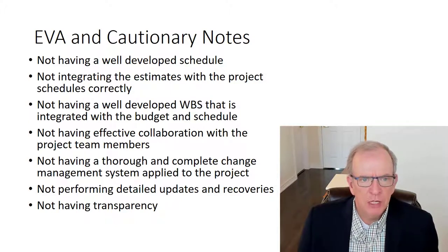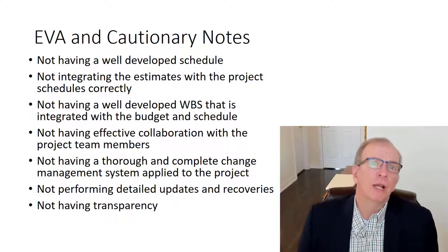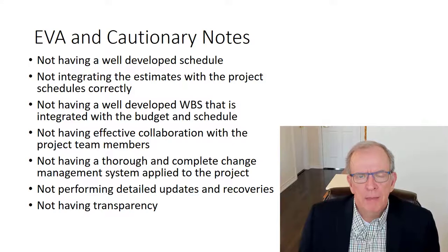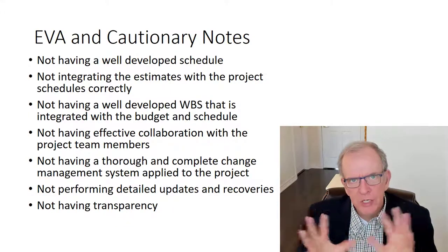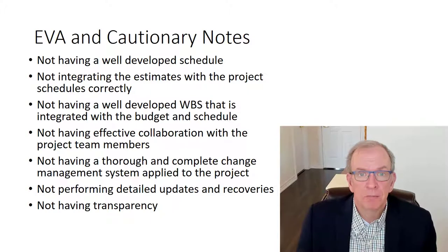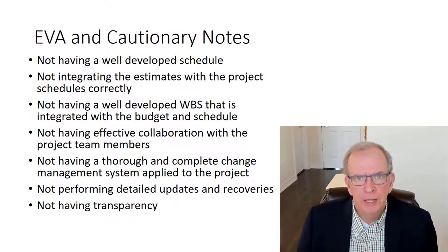Things like making sure that you don't have any open ends on the activities, that everything is properly connected, that you have a proper and effective critical path, that there are no basic errors in the original baseline schedule and baseline cost loading. You have a full integration with your project managers, your site team, your estimating team, your scheduler, that there's good collaboration and understanding and checks and balances in place. It really requires a systems approach to be successful at implementing earned value analysis.